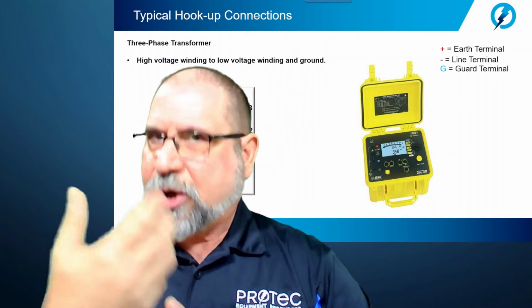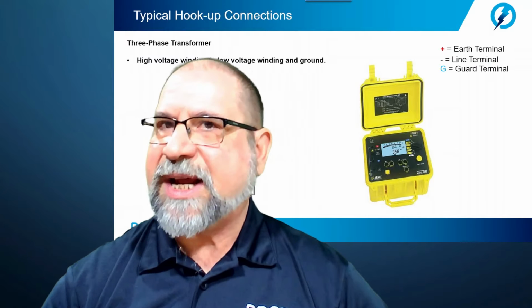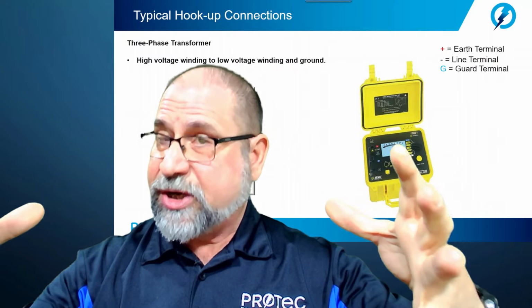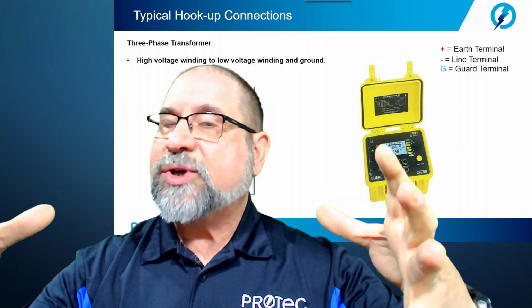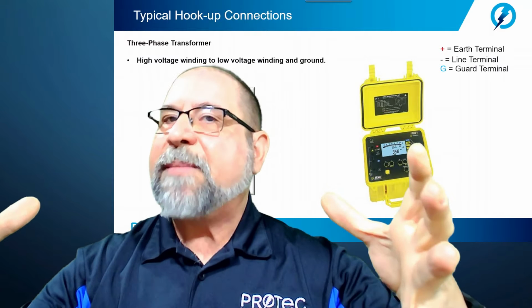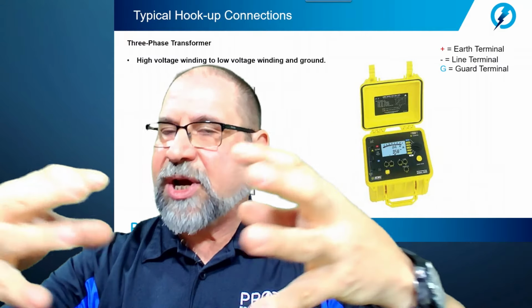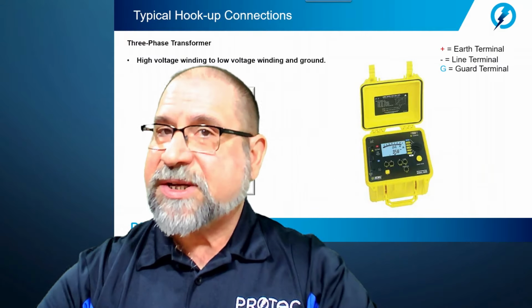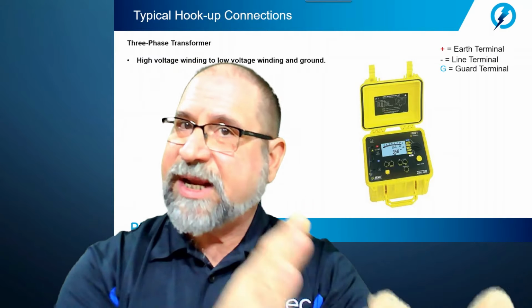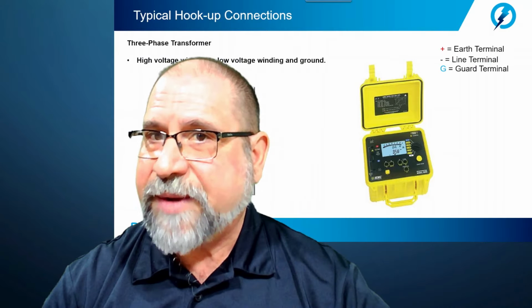So during the charging portion of the test, the magnetic field is being formed. Nothing is being induced. However, when you turn the test set off after completing the measurement, that magnetic field is going to collapse, causing movement and cutting across the secondary windings, causing an induction onto the secondary.